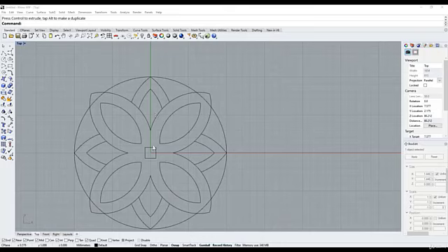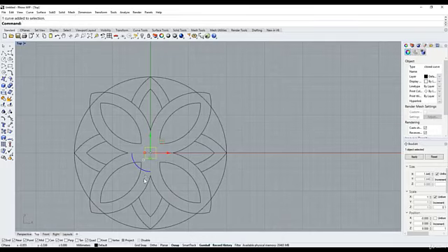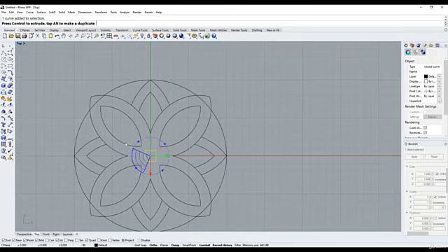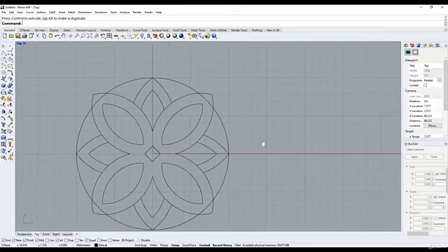Now let's say I want to rotate this 45 degrees. If I grab this blue box here and I want to snap or constrain that to a 45 degree angle, well, that's only going to snap to 90 degree increments, and that's not very helpful because being a square, it looks identical no matter which way we rotate that. If I just come over to this blue arc and just click once, we're going to have this little dialog box come up. And if I type 45, it's going to know that that's a 45 degree angle that it wants rotated. So hit enter, and there it is.